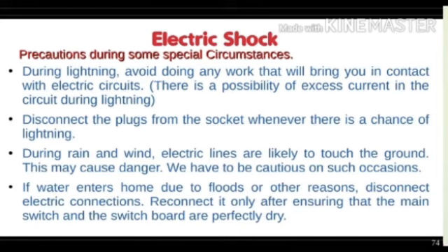During rain and winter, electric lines are likely to touch the ground. This may cause danger. We have to be cautious on such occasions. If water enters the home due to flood or other reasons, disconnect electric connections. Reconnect them only after ensuring that the main switch and the switchboard are perfectly dry.